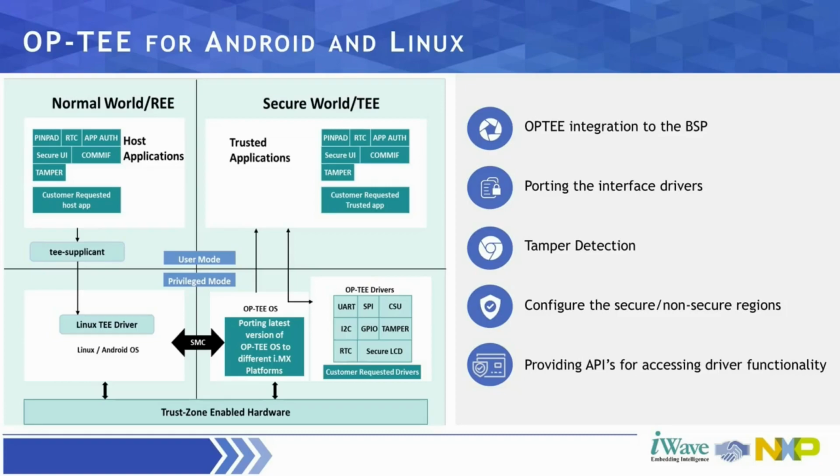For example, you might have Linux or Android running on this layer, which is completely opaque to your secure world. The transition from the non-secure world to the secure world is through a dedicated instruction called the secure monitor call, the SMC. When this instruction is executed, the CPU or the i.MX platform will enter monitor mode and will have access to all the hardware features, including the protected peripherals and memory regions. At this moment is when we can run the complete trusted environment or operating systems.